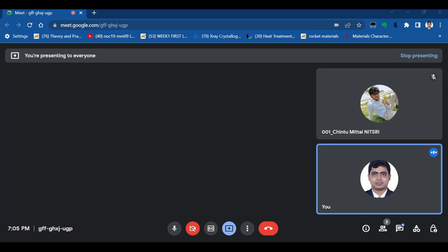So what is the condition for that? This is our sigma 1, this is our sigma 2, or sigma max, sigma minimum. These are the two principal stresses. So the condition for pure shear is sigma 1 equal to minus sigma 3. As we can see here, this is our origin 0. And sigma 2 is equal to 0. Why? Because in this example we have considered two circles, like a 3D Mohr circle. So sigma 2 is 0 and sigma 3 is this one.